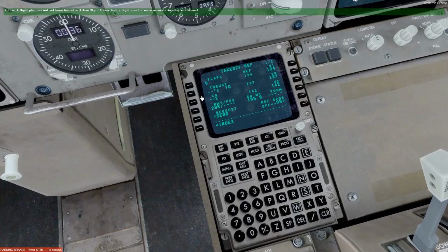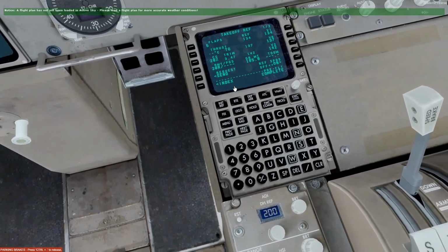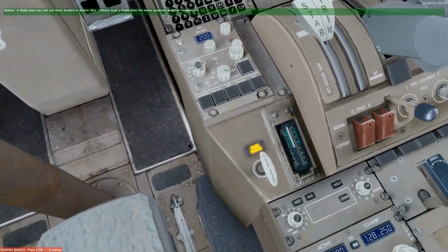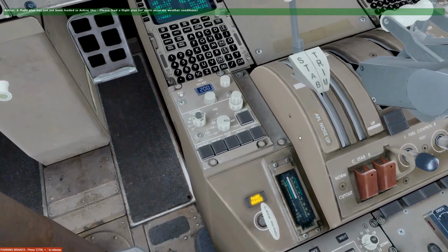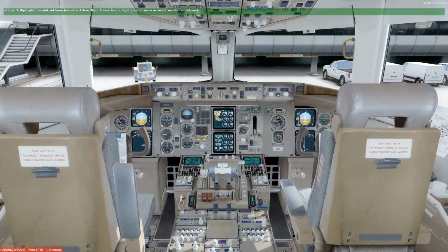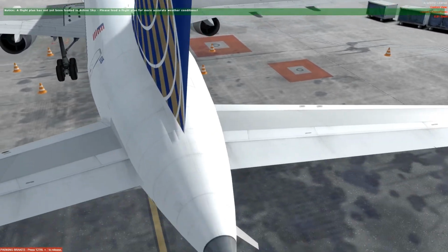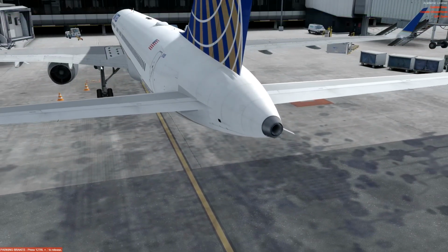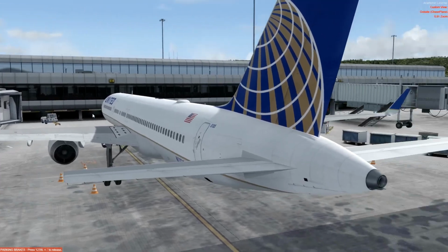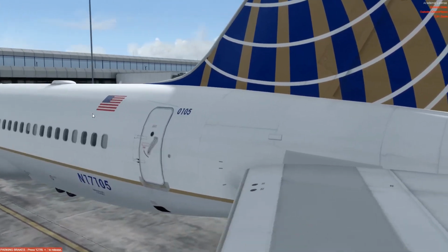And we have to select our center of gravity again, and this will display a trim number over here, which is 3.47. And that is the number that'll tell us how much we'll have to trim our horizontal stabilizer, which is, I'll show you, this thing in the back of the airplane over here, and it can be angled differently.